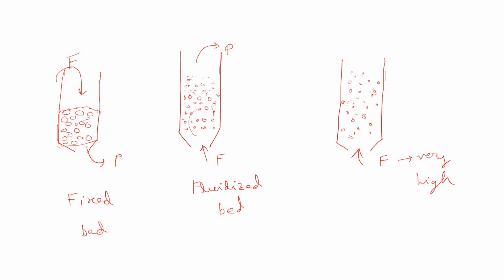And due to this chaotic mixing, there is no direction of the particles, where will they go, and this bed will expand throughout the size of the reactor, okay, but after some time you will see that at very high flow rate, some of the particles will fall out of the bed.